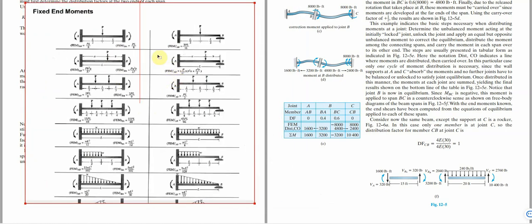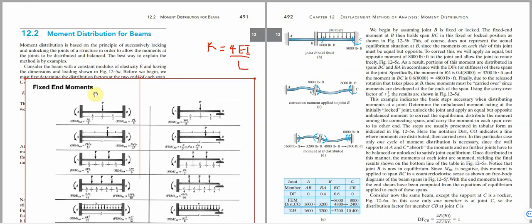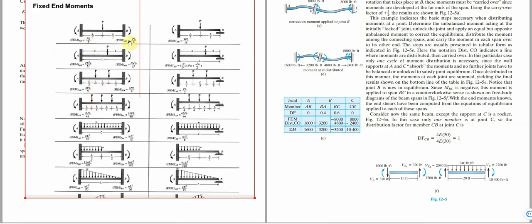And what it means is that, let us consider this as a beam. We believe all the ends are fixed, so the fixed end moment for when we have this kind of loading condition where our P is at the center is PL over 8, and likewise for fixed end moment for B2 is PL over 8.